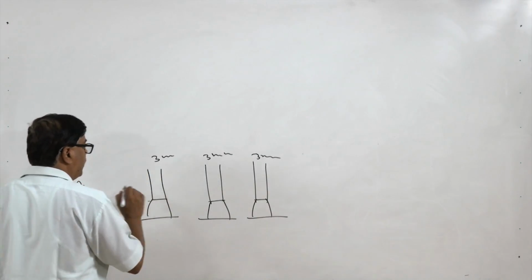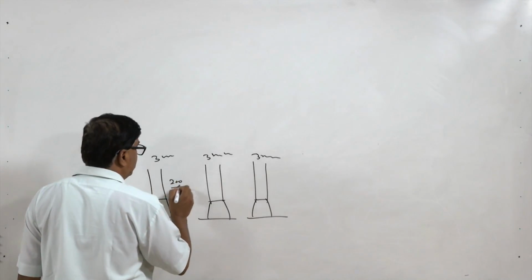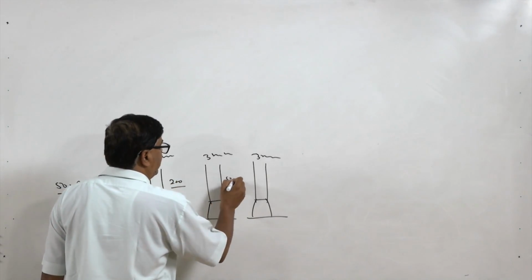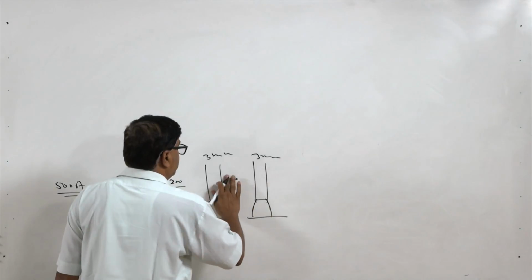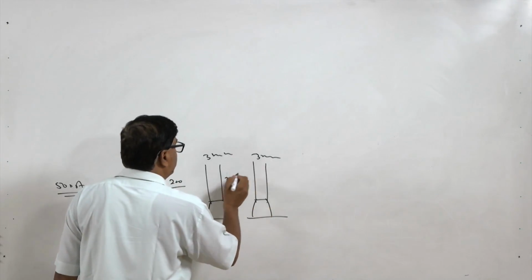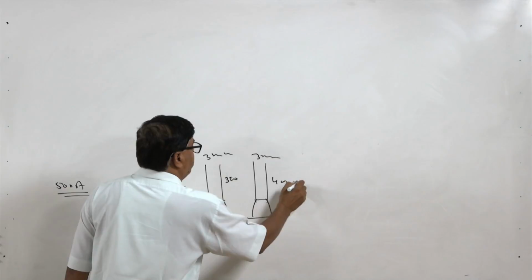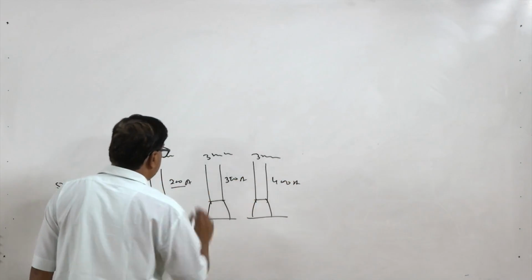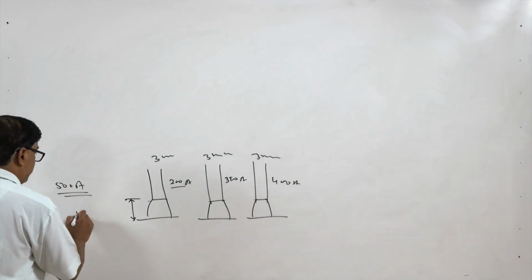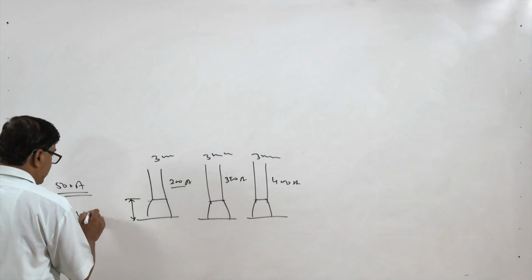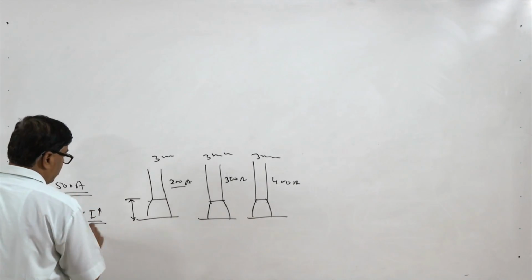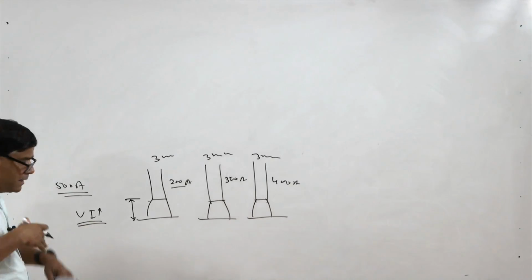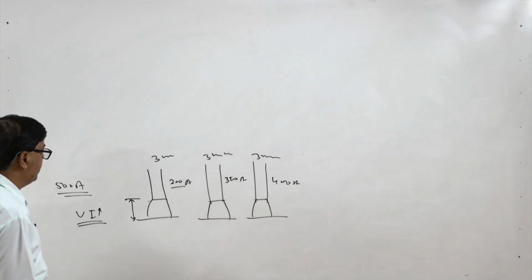So, changing the current, say 200, 300 and 400 amperes. Increasing current will simply increase heat generation, since the arc voltage is fixed and I is being increased, under identical conditions of speed.